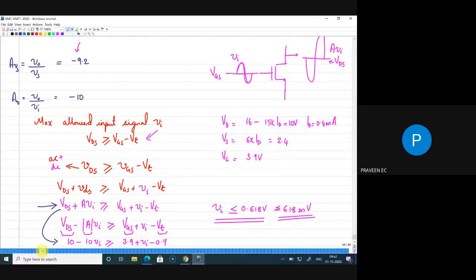Right, or it is with the understanding that if your input signal is growing in the positive direction, if you have an increment, output is also getting amplified, but you are getting it in the opposite direction first. So just to accommodate that, either with understanding that when your input goes plus, your output will go negative, that can be one thing, or when your input goes positive, your output will also go positive, but A is negative.